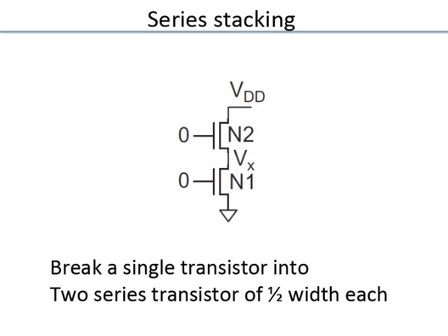When someone says I've reduced power, immediately you should think, okay, what is the cost? Something has happened, delay has gone up. Most of the techniques will always trade off power reduction versus speed reduction, or delay increase. Because now in this path, delay will increase because the pull down resistance is larger.